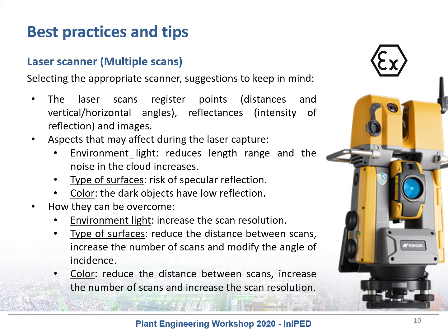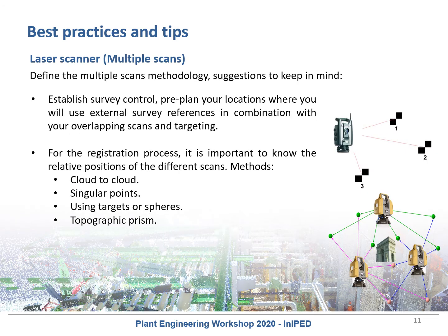At this stage, one of the most important items to take into account in order to obtain a good result in the unified point cloud is the scan methodology to apply. Remember that there is a strong relation between the geometry of the object or the scene to scan and the methodology you have to apply.